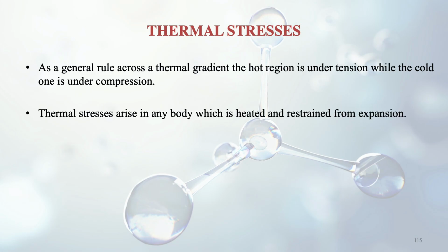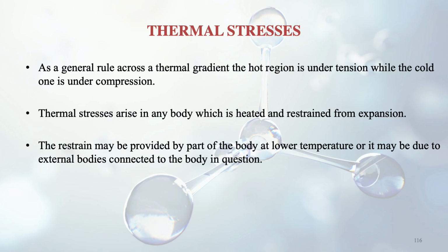Thermal stresses arise in any body which is heated and restrained from expansion. So whenever you are restraining the specimen, then stresses will come. Like in the very first module we discussed, you may apply a force and there is a certain restriction, then only stress comes in. The restraint may be provided by a part of the body at lower temperature, or it may be due to external bodies connected to the body in question. So till now we have discussed the internal type, now we discuss the external bodies type. So, stresses due to external effects.